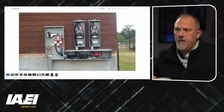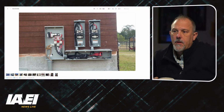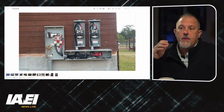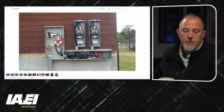In this case, I believe those are 2 circuit breakers. So those conductors are not protected from short circuits, but they are protected from overloads. But they're unprotected conductors, and we have rules in Article 230 that specifically help us address what do we do with unprotected conductors.